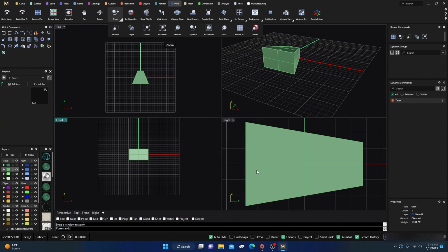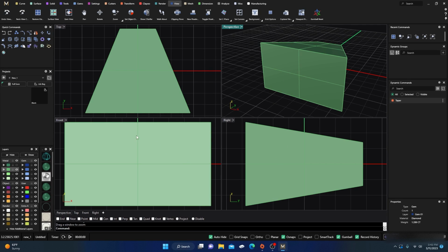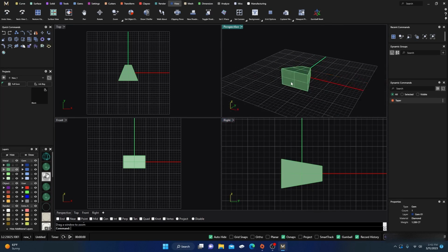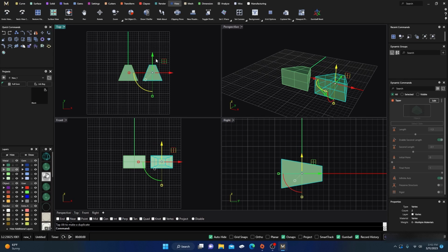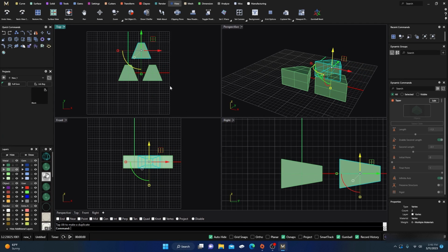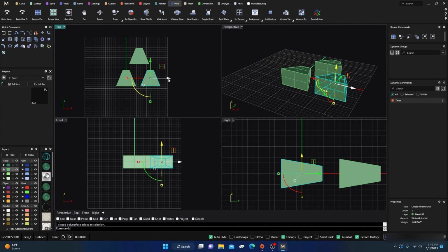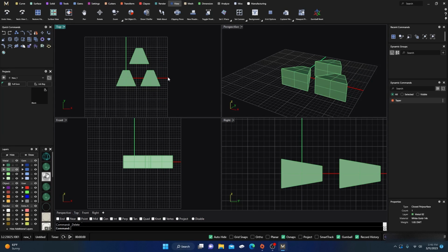Because the next one, if they're all kind of all over the place and you're kind of getting lost, it's real easy, just all extents, and then it will just snap everything back into any objects that you have. So from here, I'm going to hold down Alt and drag me another one, and then hold down Alt again and drag me another one. So I just made duplicates of these items here by clicking on it, holding down Alt, and then clicking my gumball and then dragging one out, right? And I'm going to delete that one there.